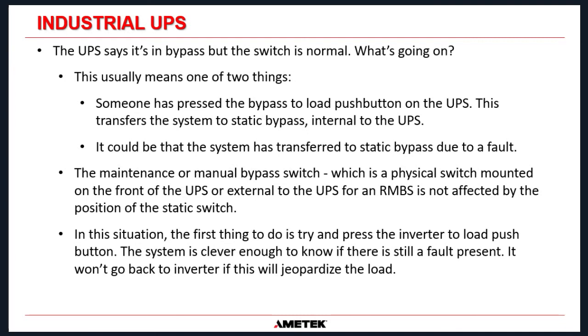Now remember, the maintenance or manual bypass switch, which is a physical switch mounted either on the front of the UPS or external to the UPS if it's an RMBS, is not affected by the position of the static switch.